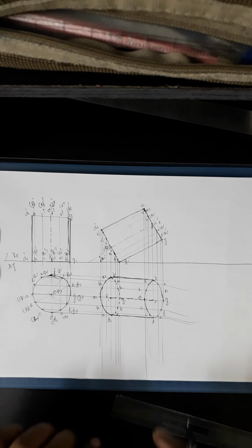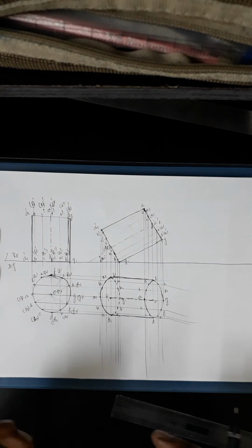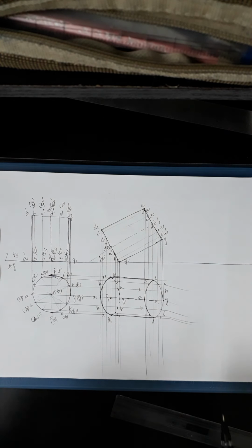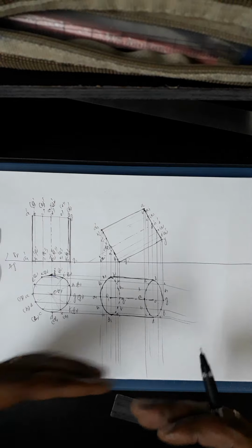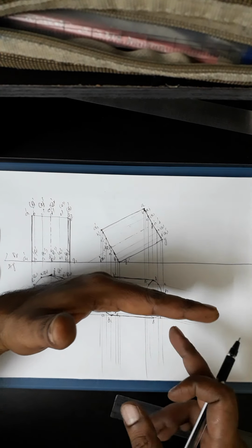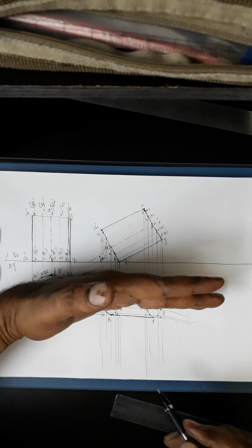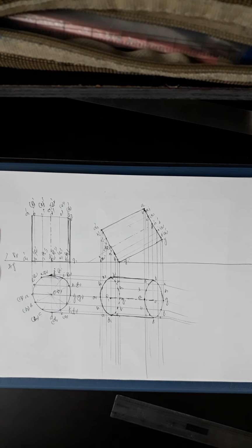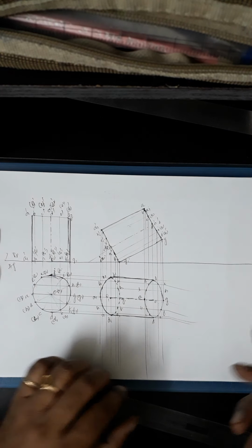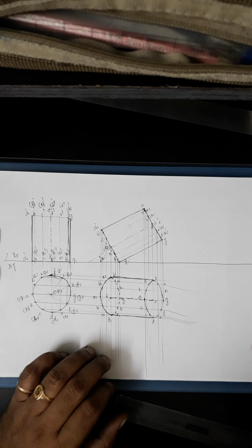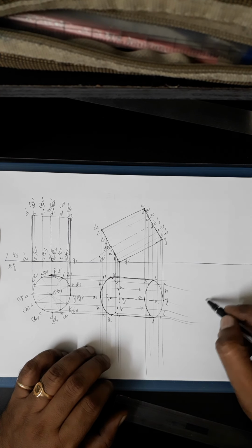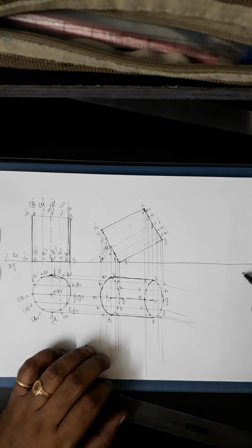If the top view of the axis, or the projection of the axis on HP, is inclined, or the plane containing the axis and the generator passing through the point on which it is resting, GG1, is inclined, then you need not take beta. Whereas here you have to take beta. I'm not going to draw the complete view. So in that case you have to go for taking beta.